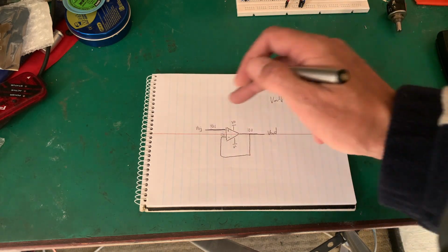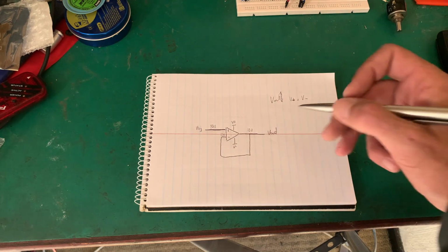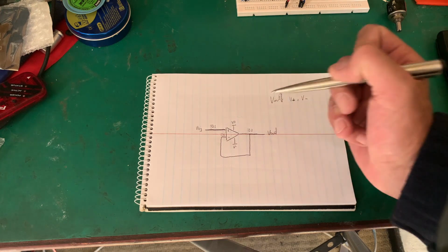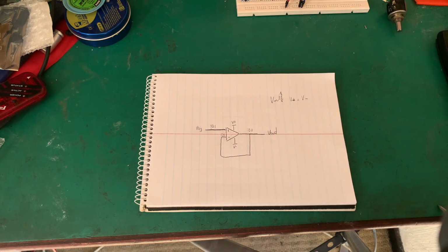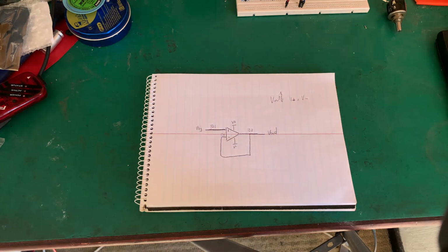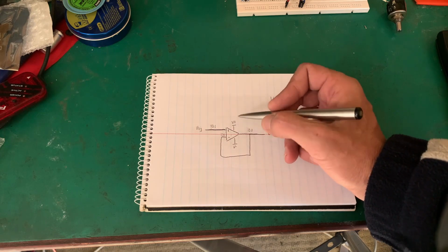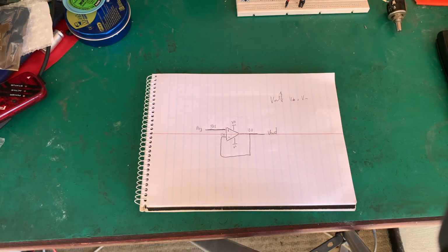Well, it's not going to work, so I can put this buffer in between. The high impedance will stop here, and of course now we've got a low impedance to drive a high impedance load, which is a very good thing for an op-amp. But also if I wanted to do signal isolation and things like that, it's a fair use.